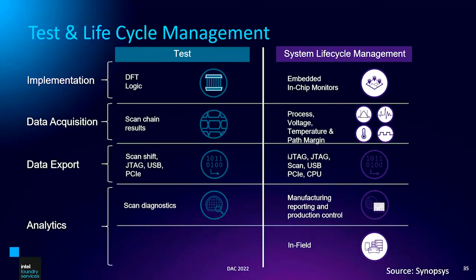This slide is courtesy or source of Synopsys as well, and thank you, Ming, for this slide. He puts out this very nice framework from implementation, data acquisition, data export, and analytics. So in terms of test, you have your DFT logic. You've got your scan chain. You have different LFSRs and BIST. You've got your data export. It could be JTAG, USB, PCIe, you name it. And then, of course, you have your analytics on the outside of your port that's pulling all this data together.